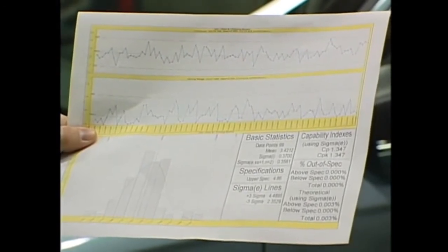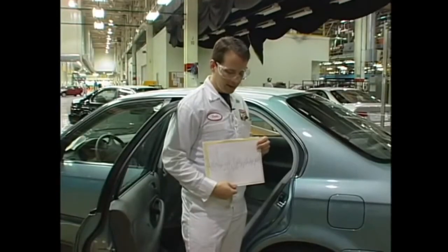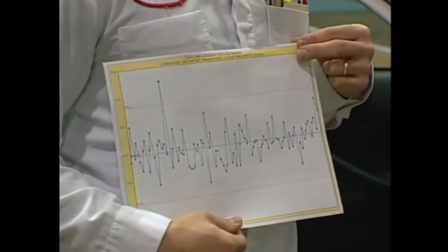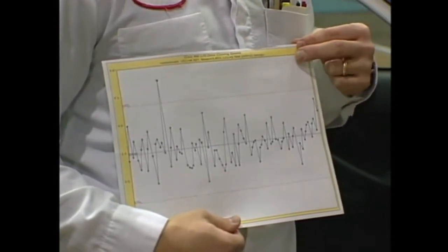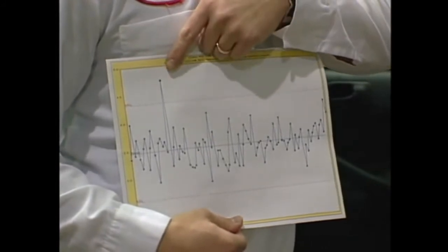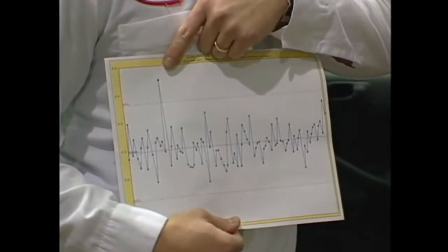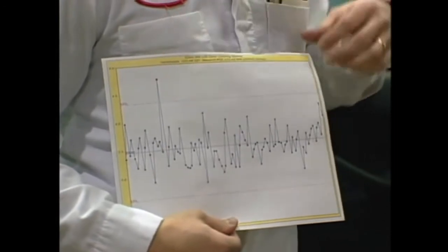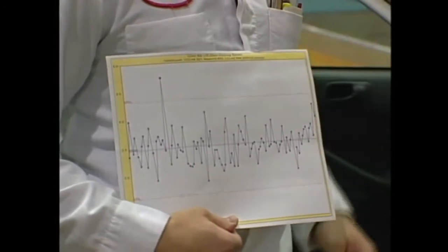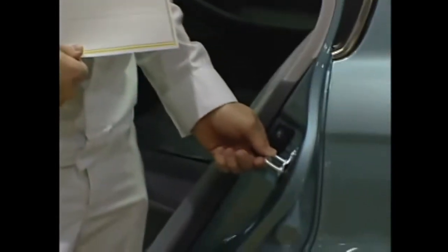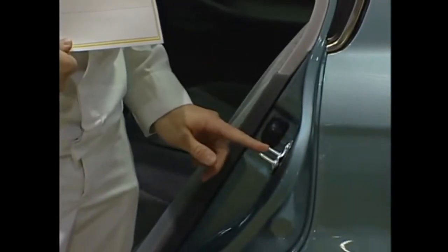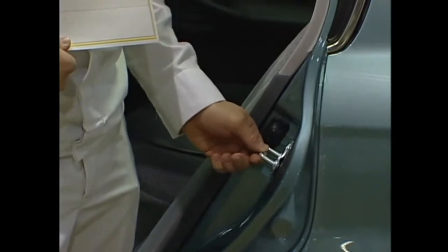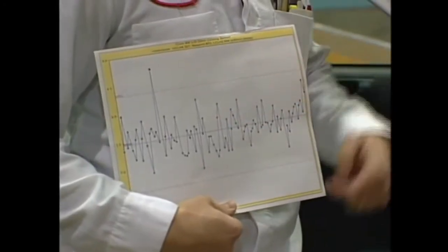During one test, a result extended beyond the upper control limit on the control chart. This indicated that one door on a certain car took an unusual amount of speed to close the door without slamming it. The data suggested there was an assignable cause potentially present. This assignable cause was investigated and it was found to be a problem with the fixture used to install the striker. When the striker is slightly offset, it will cause the door closing speed to be higher than normal.